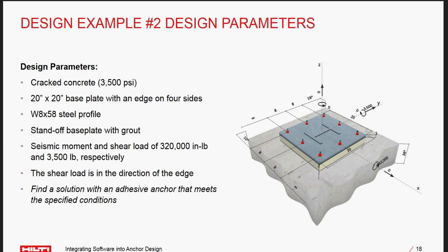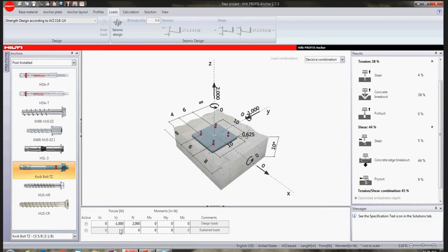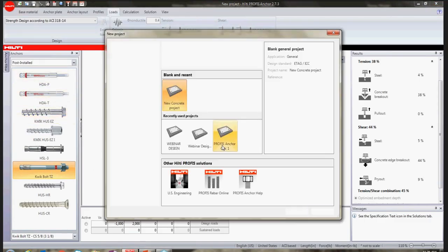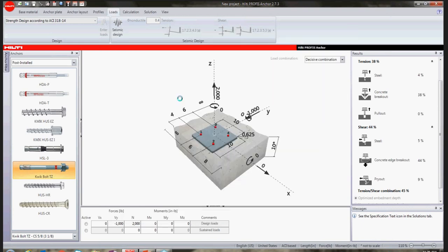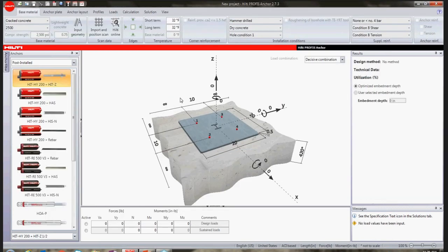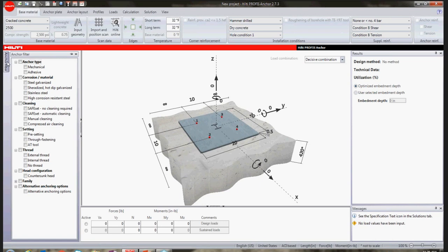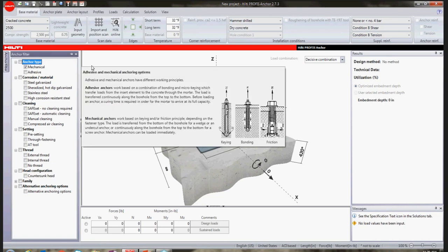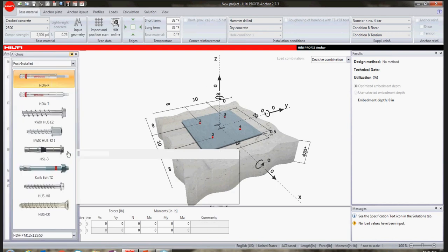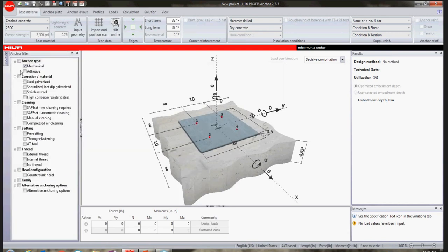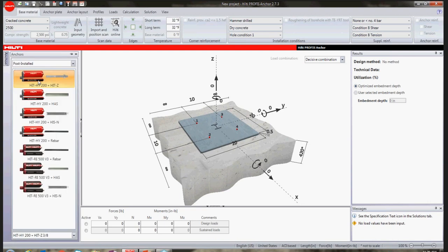I want to point your attention to the tension load section 3 here, where we see our steel strength, pull out and concrete breakout. So earlier, before I ran the calculation, I said, here is what our utilization is. What is our utilization? This is a nice, clear picture of what that utilization is. Focus on the load column. This is our highest factored tension load if we're looking at steel strength, or our factored tension load of the anchor group. And then we see our capacity of the anchor system. So we have the load and then the capacity of the anchor system. And then that utilization is simply a percentage of the ratio that's been dividing the load against the capacity.